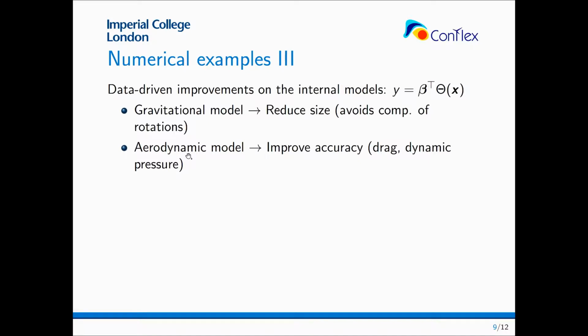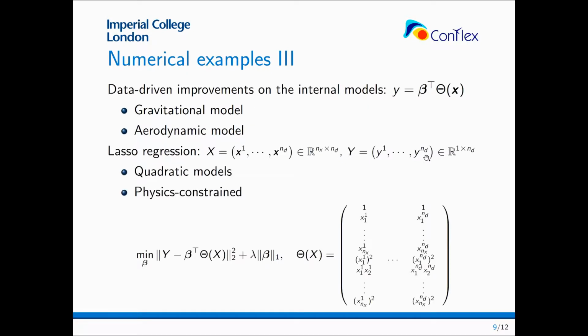For the aerodynamic model, we have identified that the linear reduced order models are unable to correctly predict forces, especially induced drag, and also the linearized formulation is transparent to variations in the dynamic pressure.